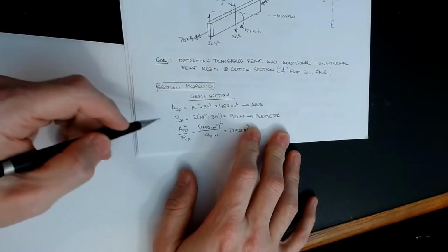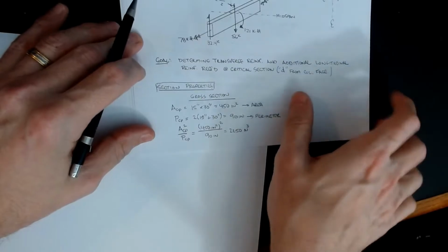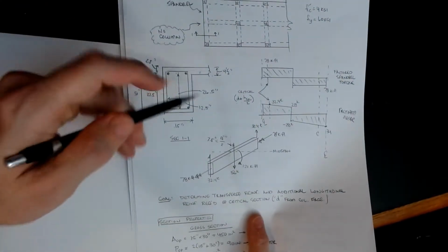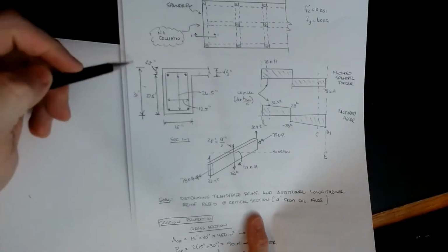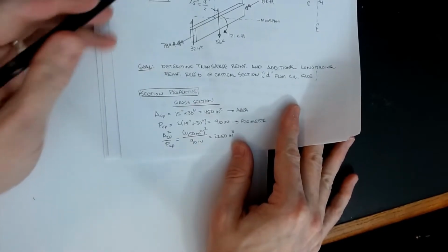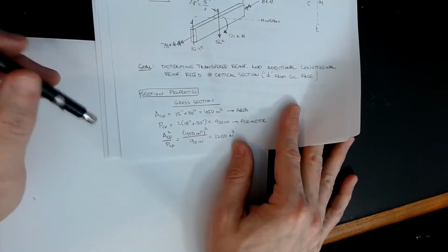and these are all those variables, the alphabet soup that we saw as we were starting to calculate those based on the cross section. So this is now how you calculate those values. Remember we're looking at this picture, 15 inches wide, 30 inches tall. So the ACP is basically the gross area of that section. That's 15 times 30, it's 450 inches squared.